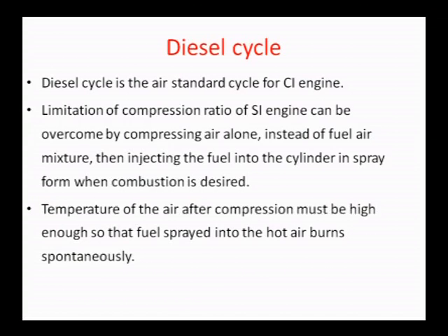So, that limitation can be overcome by compressing air alone instead of fuel air mixture, because when you compress the air fuel mixture beyond certain limit, then a destructive combustion takes place, that is detonation. Therefore, you cannot compress the air fuel mixture beyond certain limit. So, here that can be avoided by compressing the air alone instead of a mixture of air and fuel, then injecting the fuel into the cylinder when the combustion is required. So, fuel is injected at the end of the compression stroke.